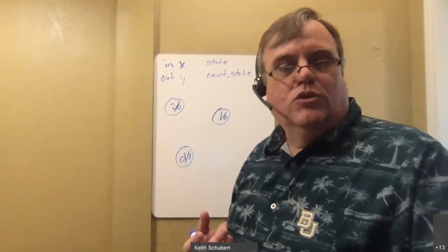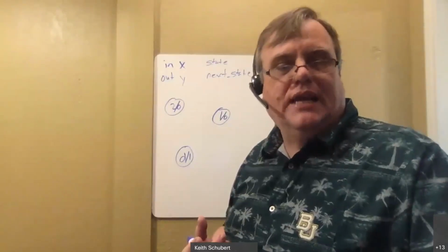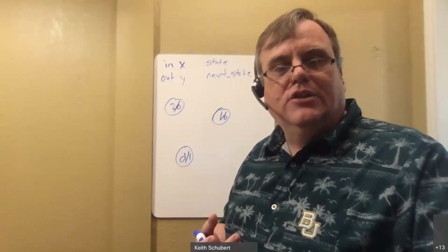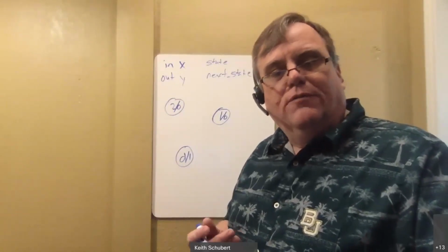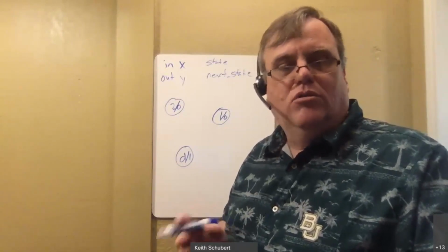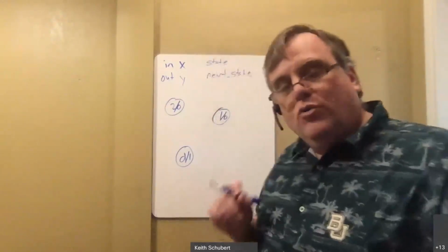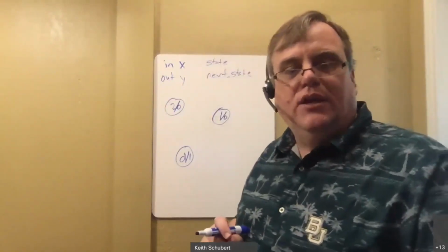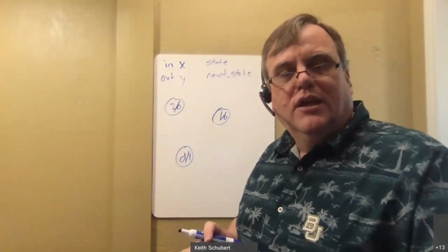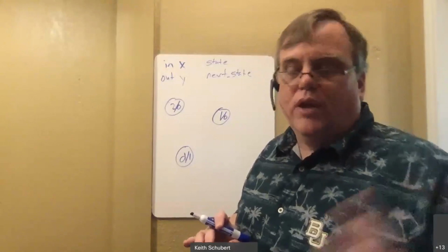For the next state, which will determine the arrows, I look at state 2 and I see that the next state will be defined by this kind of interesting notation of curly bracket X comma 1-bit binary 0, close curly brackets. The 1-bit binary 0 specifies only a single bit of 0. That tells me that there are 2 binary bits that are set, and the arrows will be X comma 0, or X0.